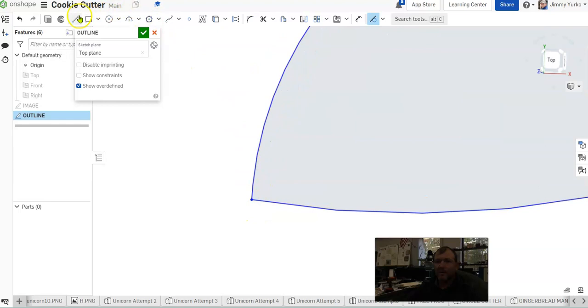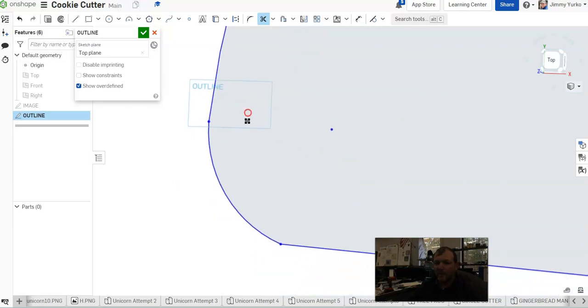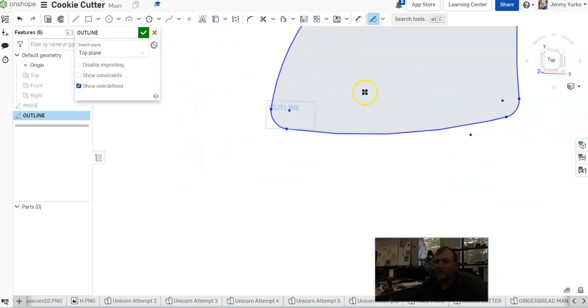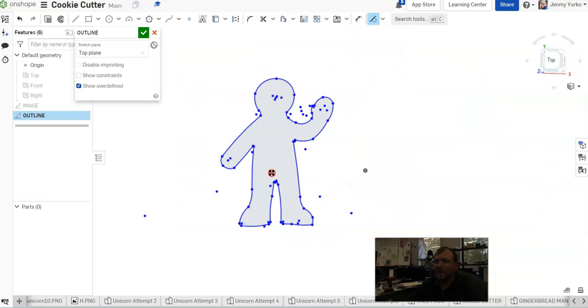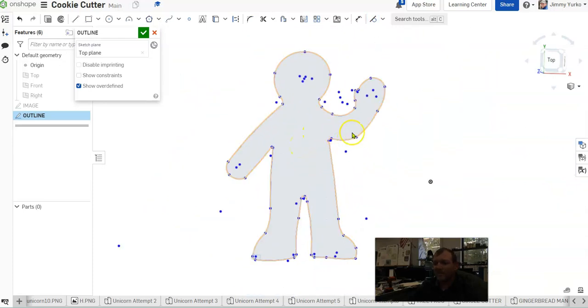I'm going to go ahead and draw a 3-point curve to close this out because I don't like that. And we're going to use the trim tool to cut that off because it's way better without that. And get rid of that. There we go. And we'll go ahead and tangent that out. So it is best that you make these smooth and tangent when possible. Make sure you zoom out and check, make sure you don't screw anything up. If you make a mistake, just Control-Z.